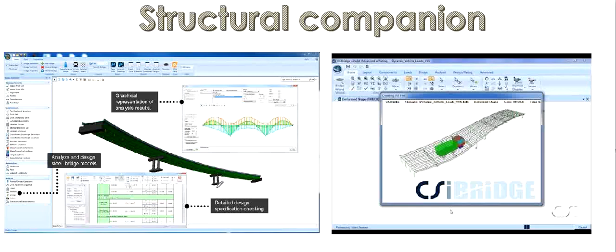So if you calculate it by hand and compare the reaction with your software, and the values are pretty similar or close to each other, then you can say the things I've done in my software are correct. If not, you have to find out why the hand calculation of the reaction and the one you are getting from the software are so different. That's one of the reasons why support reactions are so important.